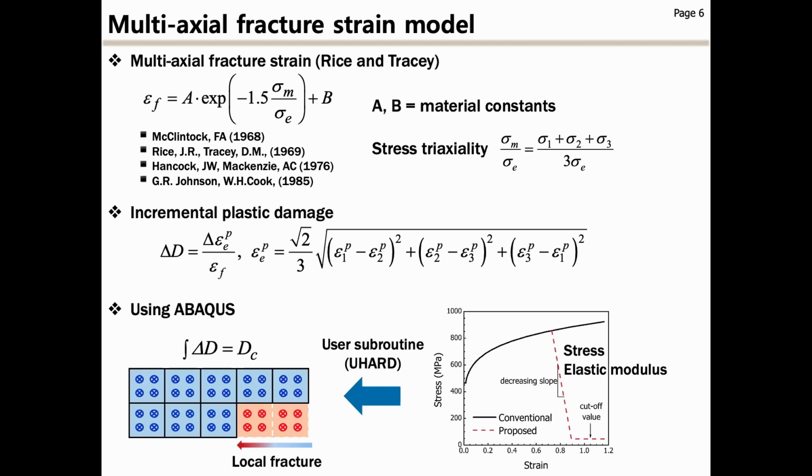To simulate this in Abaqus, a user subroutine was used to simulate local fracture by reducing stress and elastic modulus when cumulative damage reaches the critical value.